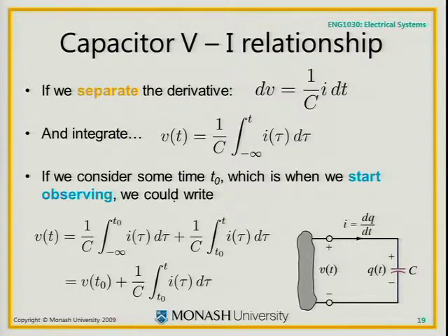That's charge building up on the capacitor. As current's flowing into the plates, charge builds up. That's what happens. We fill the capacitor, the charge builds up, the voltage increases. If the current flows in the negative direction, the charge is decreasing on the capacitor plates. So you integrate the current waveform to get the voltage that is stored on the plates. Really the fundamental theorem of calculus.